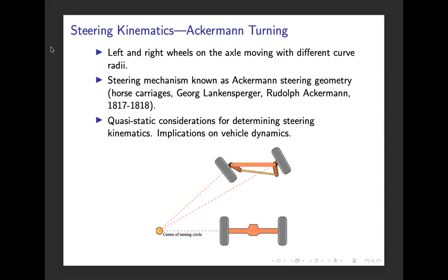Because if we would have the same steering angle, it would lead to one of the wheels having to slip all the time. But now we need to, so to say, compensate for that by this mechanical device, or mechanical construction. So that's a quite interesting invention that is still used in the design of the steering mechanism for a car.